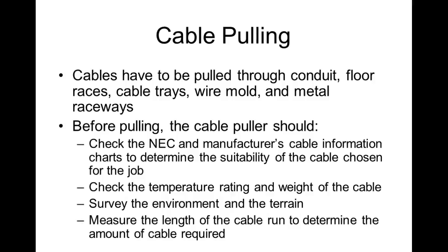Check the temperature rating and the weight of the cable, survey the environment and terrain, and measure the length of the cable run to determine the amount of cable required. We don't like splices inside conduit. So what you do is make sure that you have enough cable to make the entire run to the box that you want to go to.